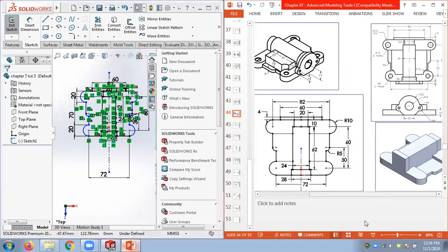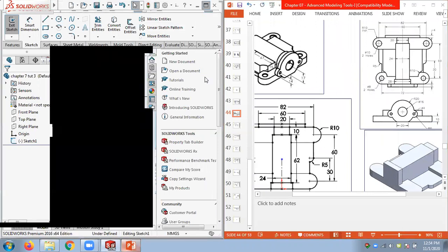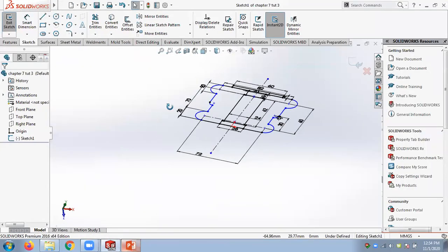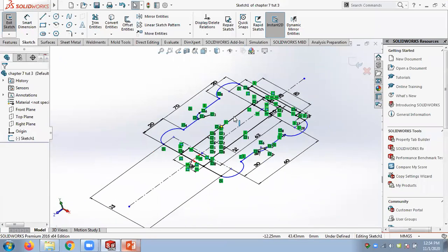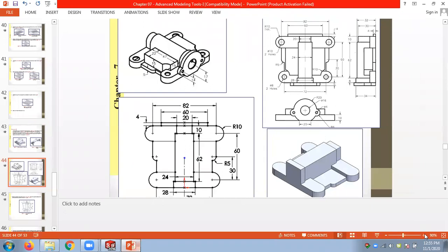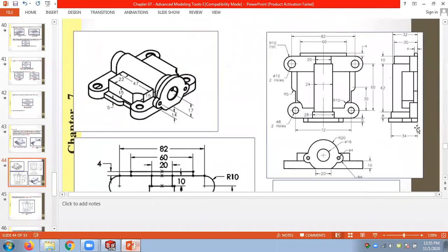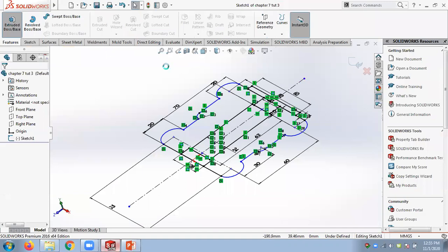Next is we have to give the heights. So heights are available. So I have the sketch at the moment with me. So we will quickly add some heights. So heights can be taken from this side view. So we have also from here, say this is 5. Then if you look at the full model, it's 32 here in the middle. So this is 32. So we can select this inside and apply extrusion.